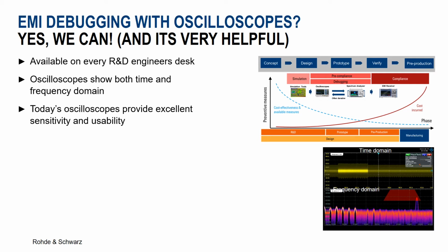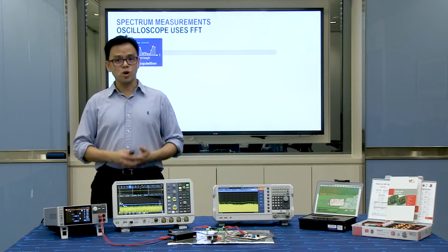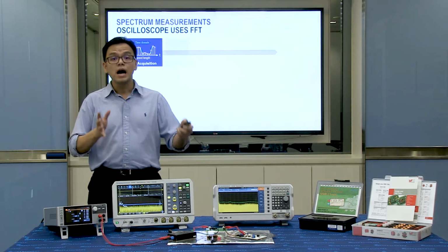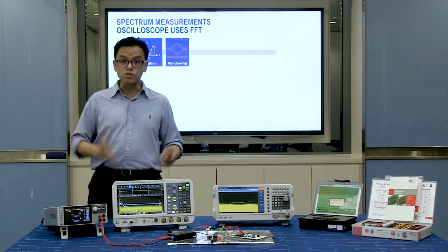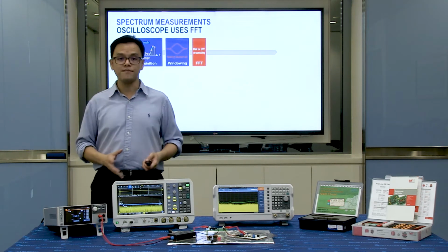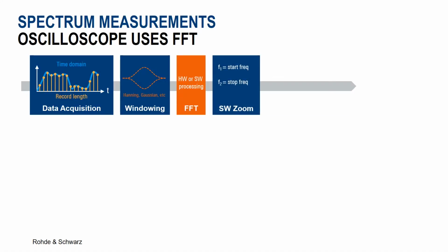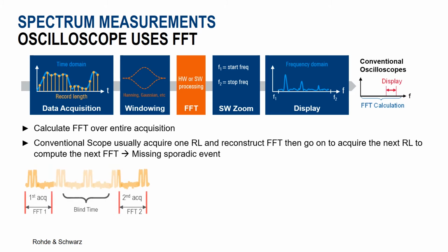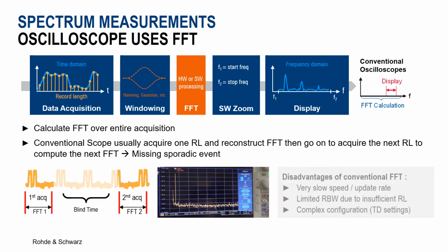the same time. In older scope technology, FFT is done by acquiring a duration of samples, applying a window filter to reduce the spectral leakage, followed by software to process the FFT, then using zoom to display the required FFT result. The problem, as limited by the technology of its time, created a slow response that made FFT measurement unfriendly.